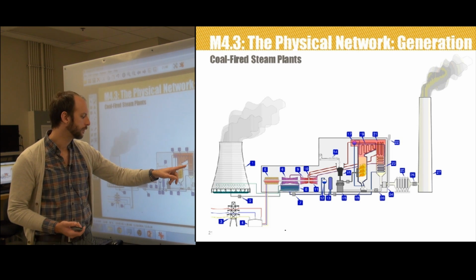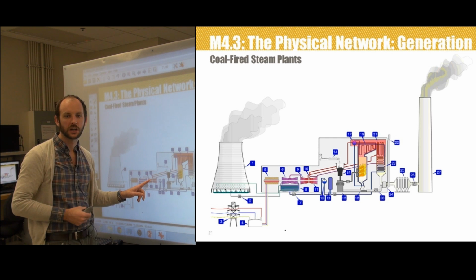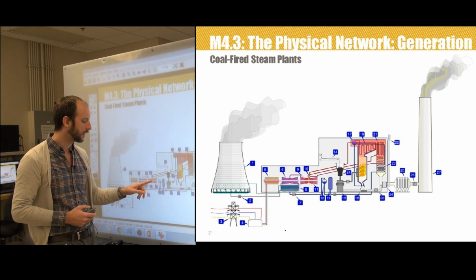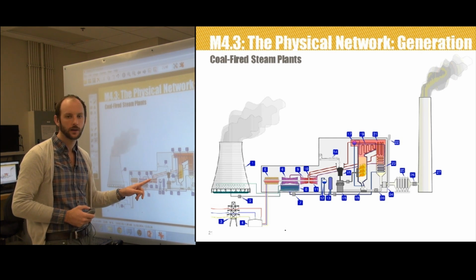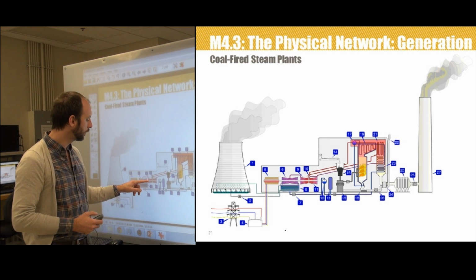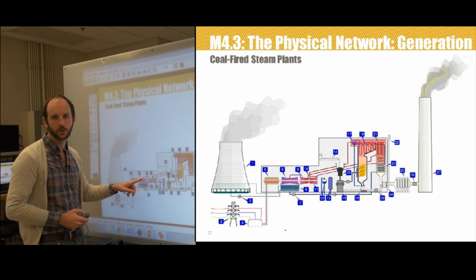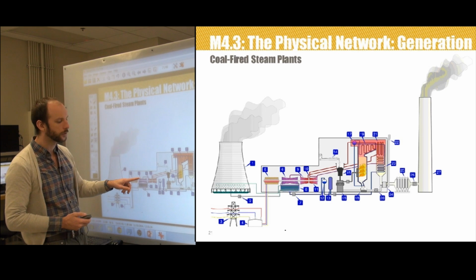And the reheated steam is then passed to what's often called an intermediate pressure turbine, number 9 here. So we see the steam path comes back to the intermediate pressure turbine. It spins that turbine as well. And then that lower temperature, lower pressure steam is fed directly to a low pressure turbine set here, number 6.